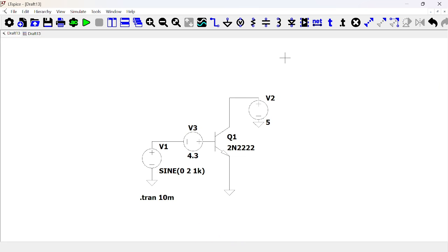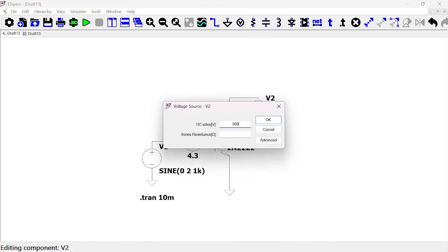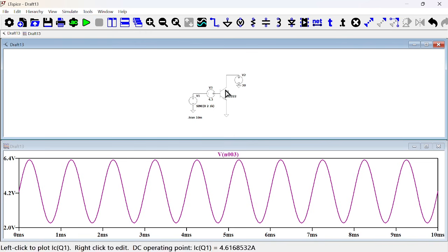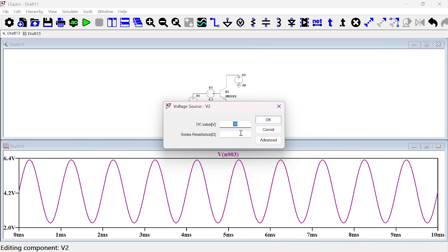And now without the resistor, we are getting an IC current of 3.8. Okay, I even expected more than that, but I think that's all that this current source can supply. Let me give 30 volts here and see. Okay, 4.8. So due to supply limitation, that makes a lot of sense. You are not going to get the 10 raised to the power 57 we would get if we used our calculator to punch in the bias current.